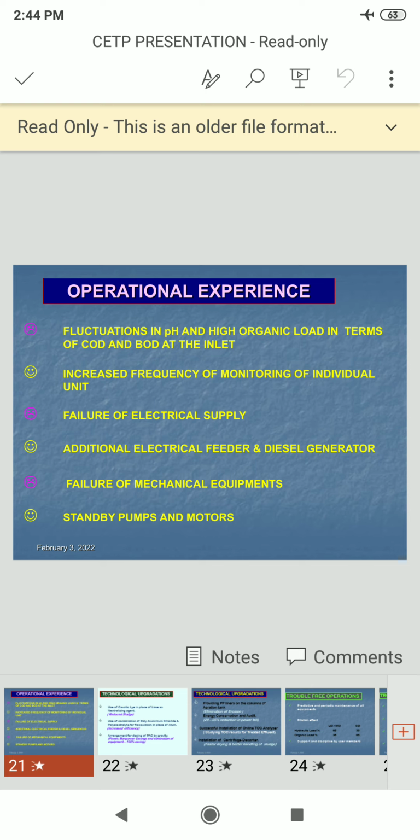Many oils can be removed from the open water surface by skimming devices, and skimming is a cost efficient method to remove most of the oil before using membrane filters and chemical processes. The skimming is done for a variety of hydrocarbons, floating grease in the waste forming solid pumps or mats. A spray bar aerator or some kind of mechanical apparatus can be used to facilitate removal.